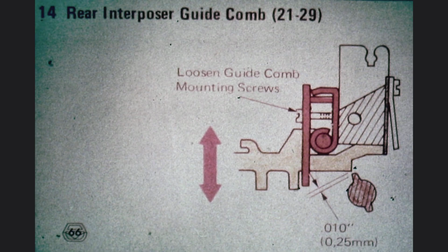Be sure to think of this when you blow out a machine with your air compressor. This is the fundamental adjustment of the keyboard. It must always be checked before any other adjustment of the character keyboard, because it affects almost all the other adjustments. The distance between the highest spot of one of the lobes of the filter shaft and the bottom rear corner of a character interposer at rest must be 1/4 of 1 millimeter.